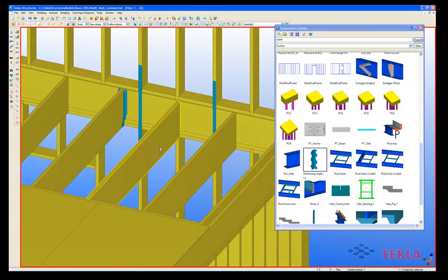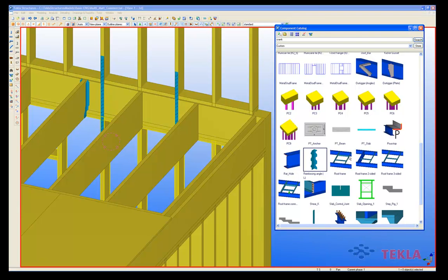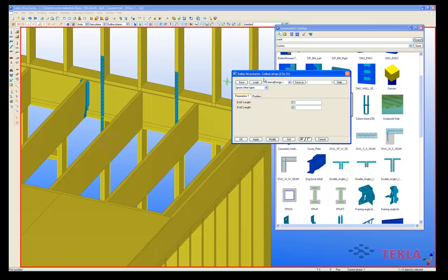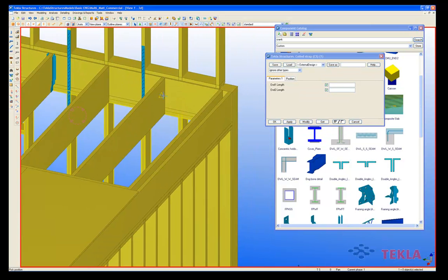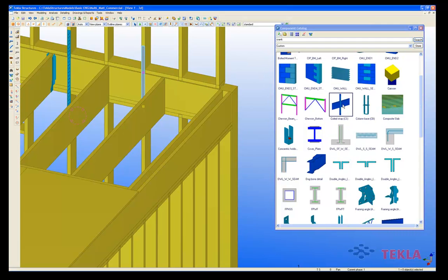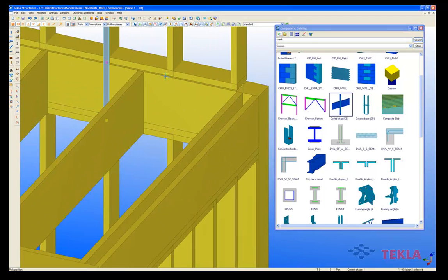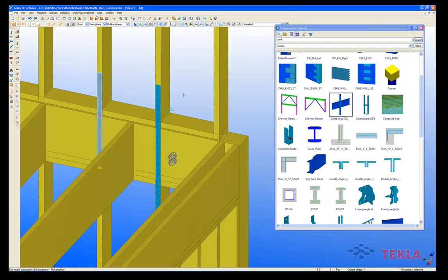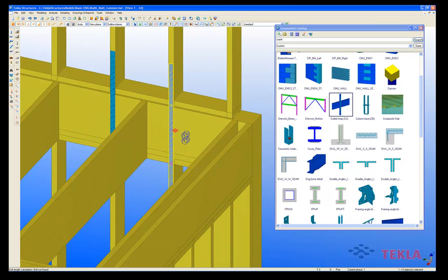Now the coiled straps that I have over here are slightly more intelligent. They're defined. Most of these are defined with nailer holes as well. So we've got some end length functionality here that I can come in and edit. If I come in and just click this one in first, and then I'll show you how that changes. Just a 2-point click over that clear span. And then the ends adjust accordingly.